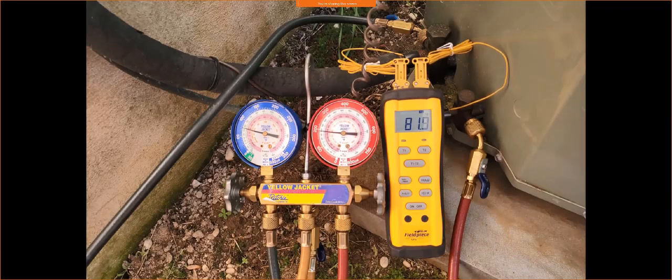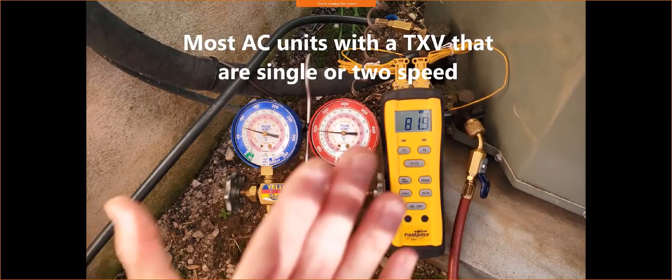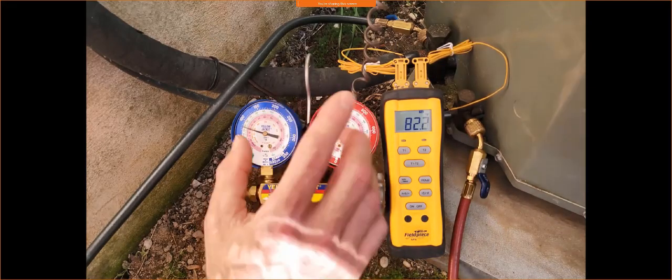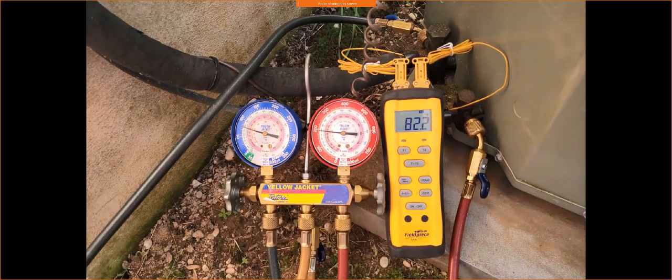So when the rating plate is worn off, I typically set the unit at 11 degrees of subcooling, because that is very close to the normal range of most outdoor air conditioning units. As you can see with this unit, we have 17 degrees of subcooling, so that's more subcooling than we need, which means that we need to recover some refrigerant out of this unit.